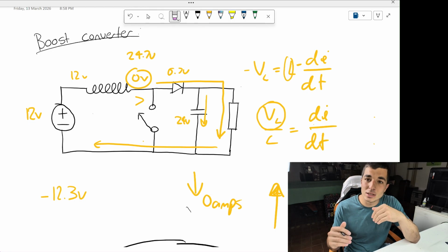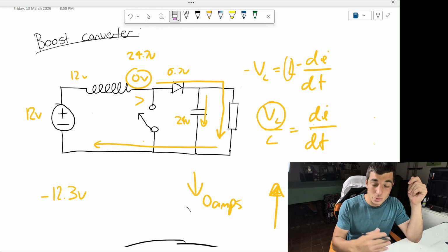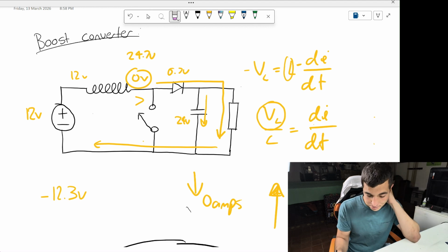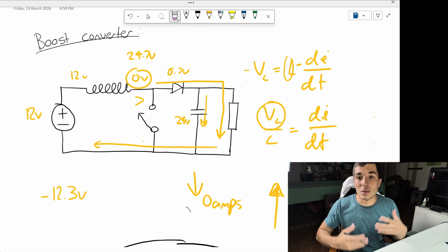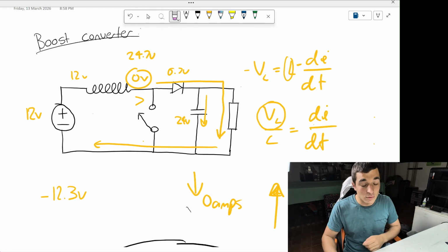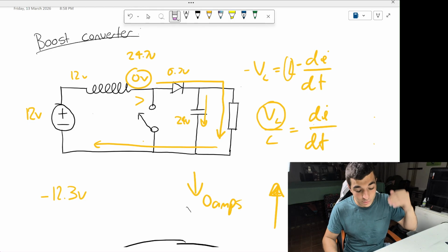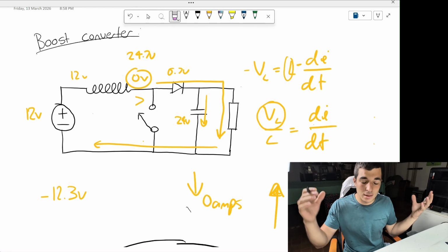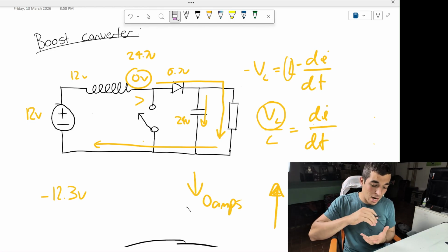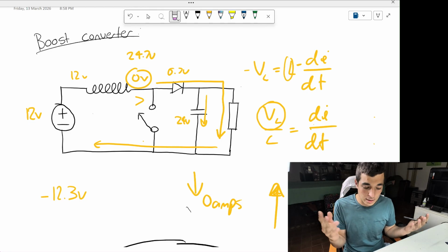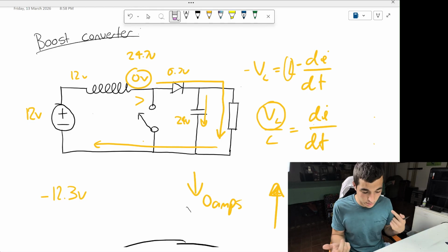And so if you want to go to 0 like that, like we do, we open that switch and allow no path to go, right? Zero amps, well, then it requires an infinite amount of voltage, which can't happen physically. So voltage will just spike until it finds a path, and then once it crosses that diode and goes through the load, then it's happy. And then the magnetic field starts to collapse until we close the switch again, we charge the inductor, and the cycle repeats and repeats and repeats.